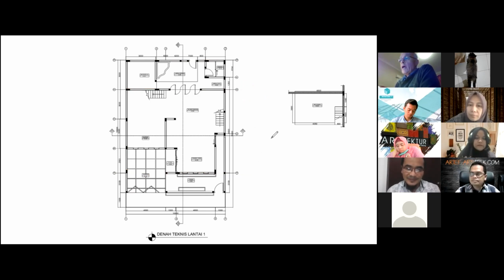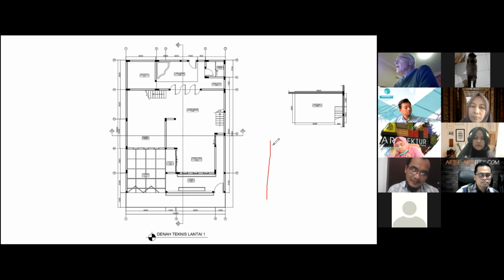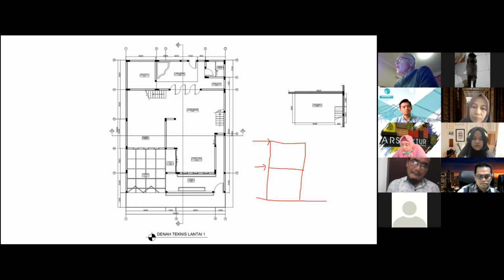Well, thank you for your question. It's rather difficult for me to answer it because I believe you can't really separate out lower structure and upper structure, because if you take, for example, a frame, it has to work throughout the height of the whole building. Like here's a frame to resist earthquake forces. And so the frame has to rise the whole height of the building in a continuous manner, and has to consist of beams and columns and rigid joints.